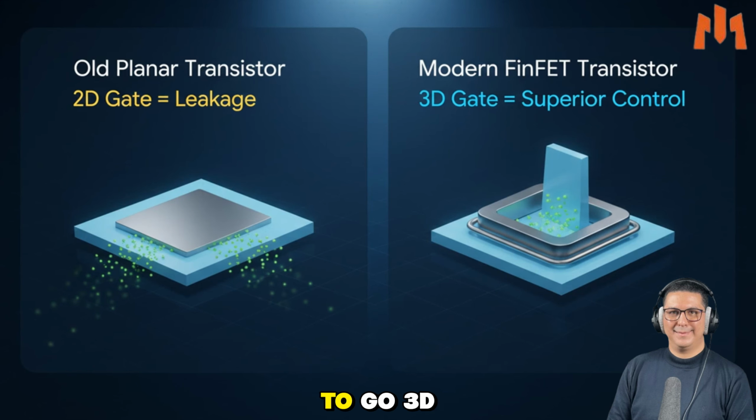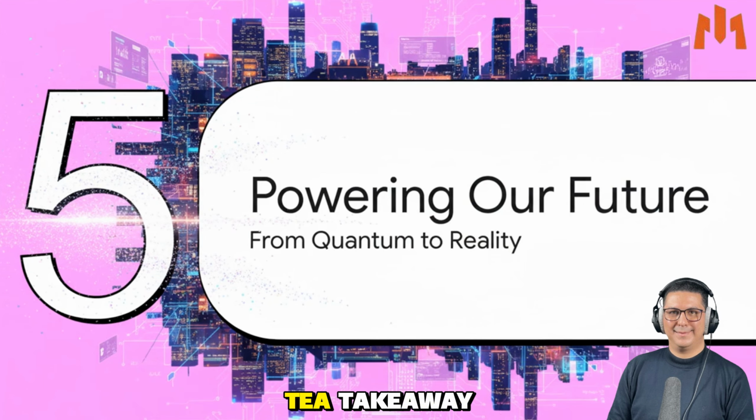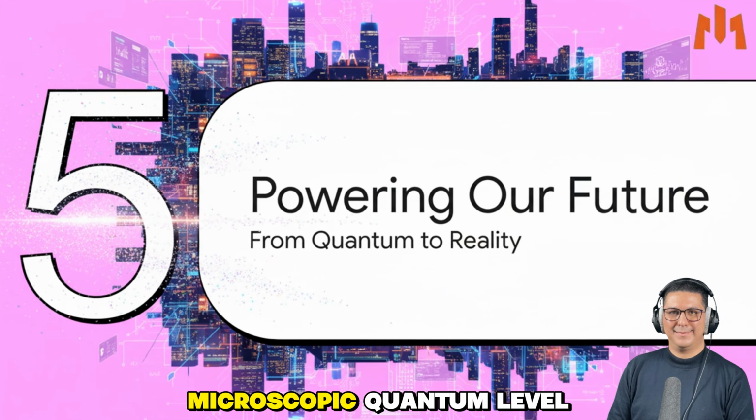The solution was to go 3D. See, the old transistors were flat, or planar, with the gate just sitting on top. But as it got smaller, it lost control. The breakthrough was a design called the FinFET. Instead of being flat, the channel rises up like a little fin, and the gate actually wraps around it on three sides. This gives the gate a much tighter grip on the flow, effectively slamming the door shut and stopping those leaky quantum electrons. So here's the key takeaway. By solving these insane microscopic quantum-level problems, we unlock massive, real-world capabilities.